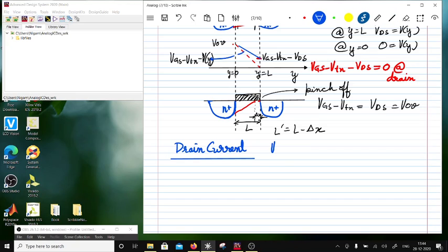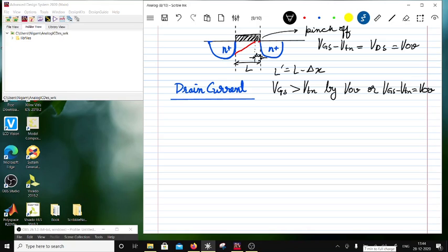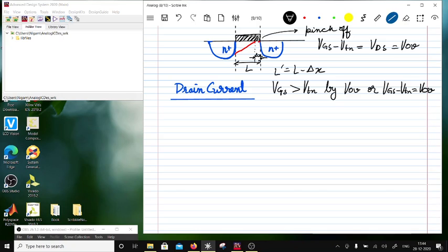So we are assuming VGS is greater than VTN by V overdrive, or VGS minus VTN is equal to V overdrive. So at that point we have a treatment for that. Let's see that. Okay, so let's derive this. To derive this, we know that the charge in the channel is given by, so I'm going to ignore all the signs.